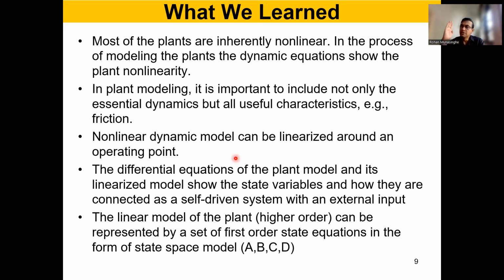Now, in this inverted pendulum case, if you pick theta equals 45 degrees, it is a very awkward operating point. You can mathematically do it, but you will not be able to get rid of the nonlinear terms there, because how can you say sine theta equals theta then? So your line of assumptions breaks. Therefore, you have to make sure the operating point is physically an equilibrium point, so that most of the nonlinear terms are actually not nonlinear around that point. It's not any point, okay?